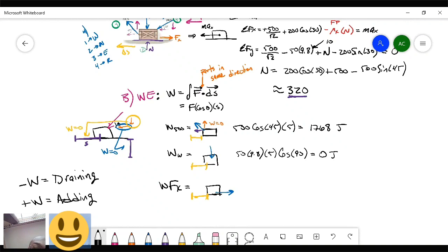And so this one's just going to be 0.2 times 320, which is friction. I got to put a negative on that because it's negative, and then I multiply by my 5 meters. Am I good with just doing 320 times 0.2 times 5, or do I need a cosine? You don't need a cosine because it's perpendicular.